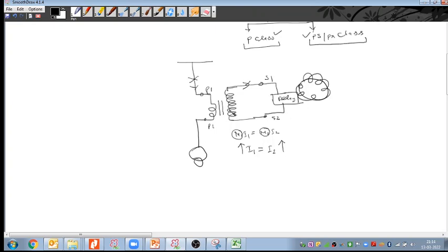But for that saturation, how much minimum voltage is required on the CT secondary side at the event of the fault, after which the CT may saturate? That minimum voltage is governed by the relay: how much voltage the relay requires to operate correctly.